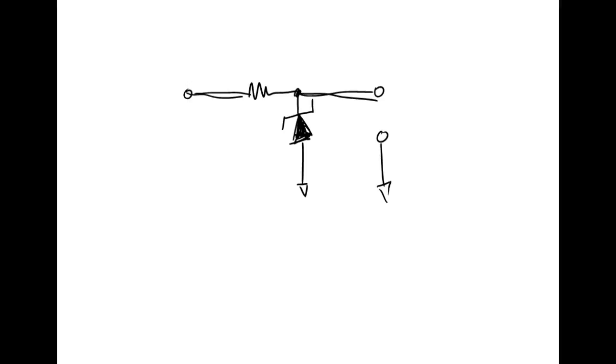So what's the first thing I need to... yeah, well, the input, the swing of the input. So my unregulated DC is going to be 10 volts plus or minus 10%. And this is DC, so my V in max would be equal to, what's that? Okay, would be what? 11, yeah. And my V in minimum would be 9, right? Okay, so these are my two.